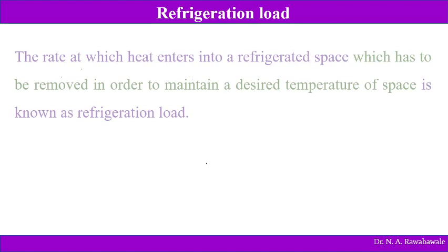So what is refrigeration load? Already we have seen the rate at which heat energy enters into the refrigerated space. Say for example, you have a refrigerator at your home. Generally this refrigerator runs continuously. Why does it run continuously? Because heat energy always enters from the surrounding into the refrigerator, because there is a temperature difference. So due to the temperature difference, heat energy from the surrounding always enters into the refrigerator. The amount of heat energy which enters has to be removed, so the removal of that heat energy is necessary.